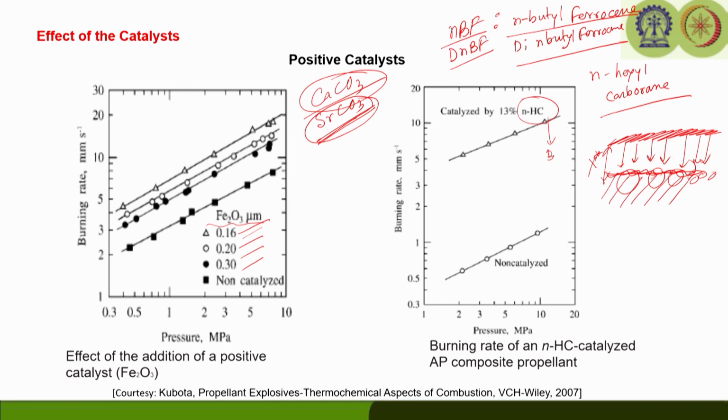If you recall, we said in the introduction part that boron also acts as fuel, because it has a very high energetic content in terms of gravimetric and volumetric heating value. So, this will act as fuel as well, which in turn is going to provide heat at the burning surface. This enhanced heat flux is going to decompose the AP particles further and the binder on the burning surface, which in turn is going to improve the burn rate of the propellant.